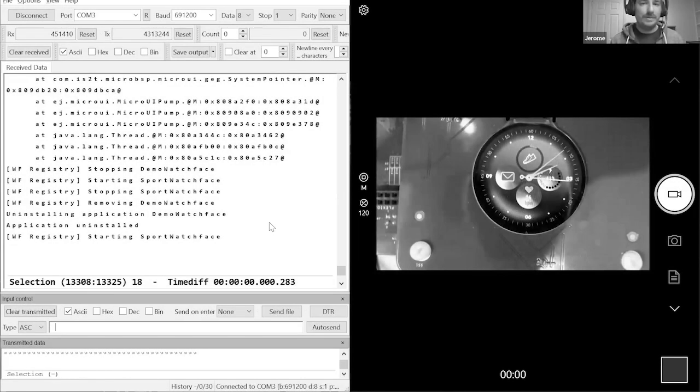You could use an MPU to prevent any kind of limit memory access, but usually it's difficult to configure. It's not very dynamic. If you add new threads, etc., you need to modify the configuration of the MPU.